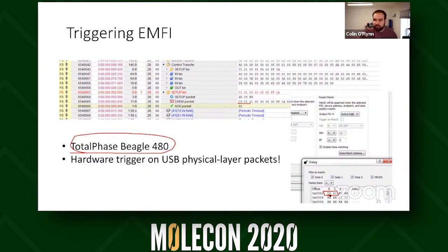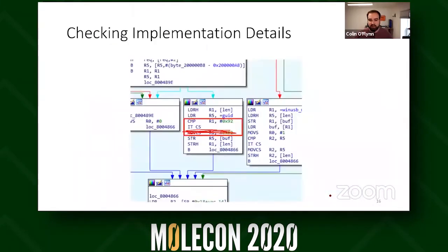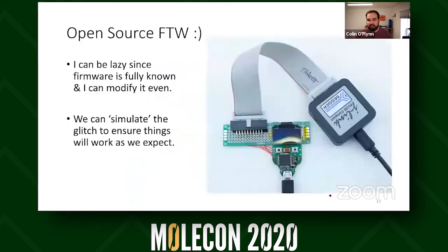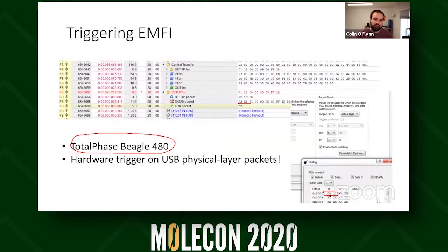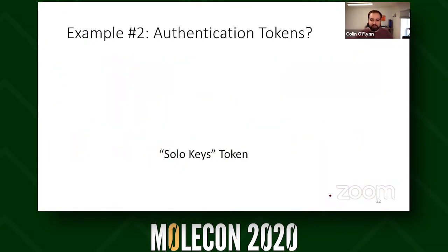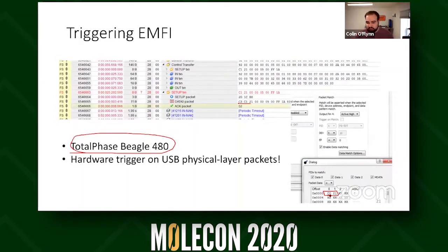This is assumed to be pretty well synchronized with the target device. In reality, there's a lot of jitter, so it actually takes quite some time to hit just the right point, because if we look at this code, it has to hit that exact point. If it doesn't hit those few instructions, it's not going to work. So in practice, I trigger from the USB packet and say, just keep trying until it works. With doing this, it will return all of the data. There are some longer talks that go through the details of this, and a paper also.